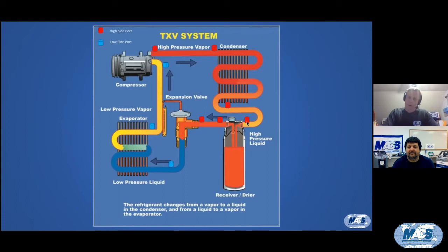And we could go along further here and check the pressure there, and that would help us isolate the restriction in the condenser. In reality, we can't do that because we're not going to have service ports in all those locations. And even if somebody was given a blank check to do that, you can't access all the locations because there's just not room on a modern car to do that.